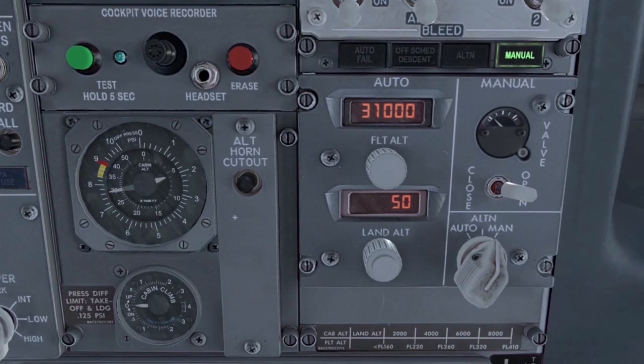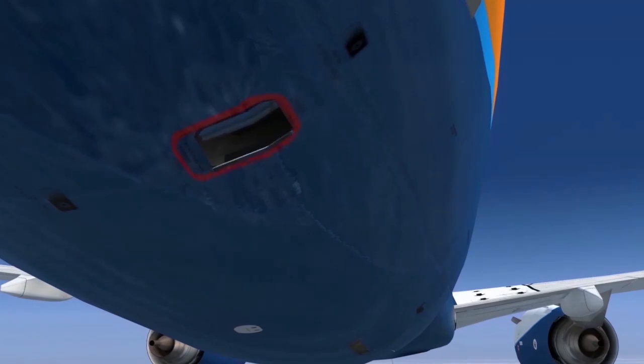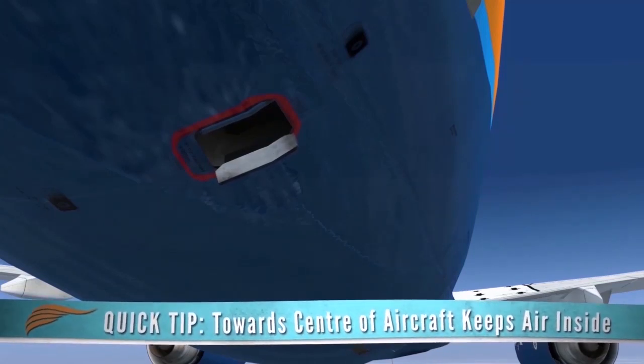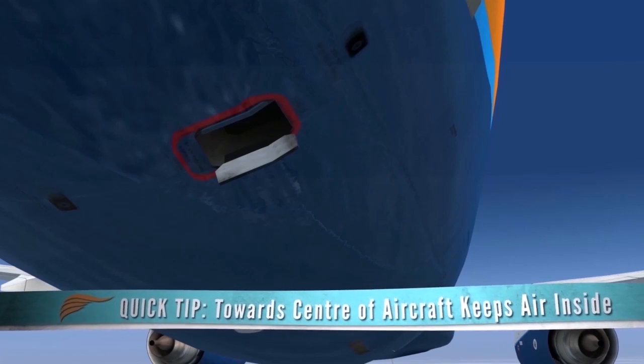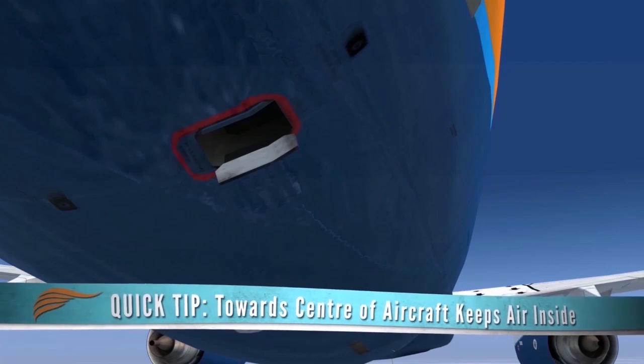This switch is spring-loaded to center, but has the following positions. Close. When the pressurization mode selector is in manual, it progressively closes the outflow valve. Open. When the pressurization mode selector is in manual, it progressively opens the outflow valve. A good way of remembering how to operate the outflow valve switch when pressure is manually controlled is moving the switch towards the center of the aircraft keeps the air inside.